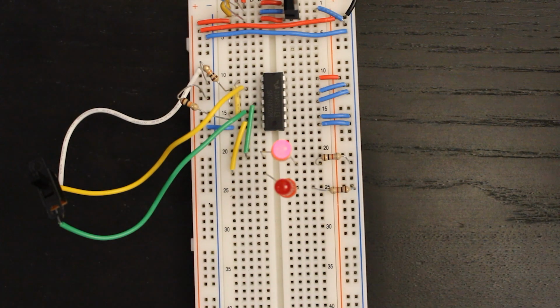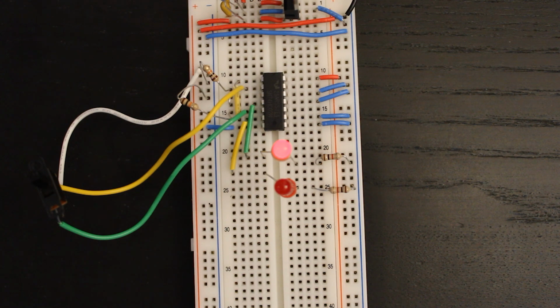Now, just looking at it like this, you might be wondering, is that NOR latch really adding much, because we're getting exactly the same functionality as we got before? But actually, we've got a much more stable circuit here, because as soon as we throw that switch, the NOR latch is changing the state of the circuit to light the other LED, and it's holding it there, and that is the key point here.